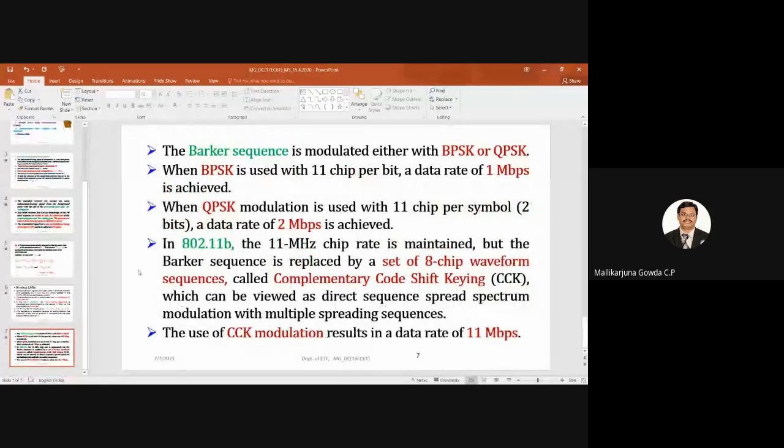Yeah. Then this Barker sequence means you should be able to visualize the block diagram of this spread spectrum. The message signal is there. First that will be spread by using a pseudo-noise code. The pseudo-noise code used here is a Barker sequence, and even that Barker sequence is specified. After that, we do the modulation, right? So that is what is done here.